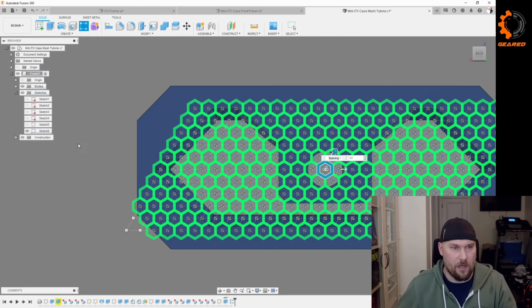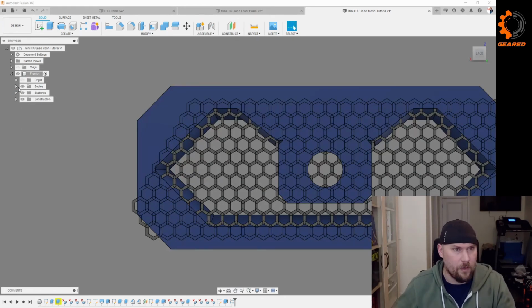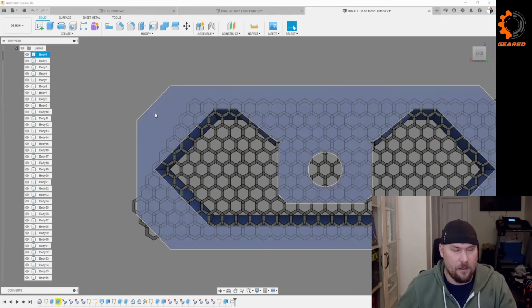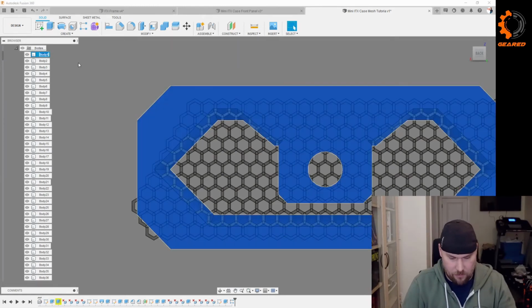It's going to create a whole bunch of bodies over here. So we are going to turn off that sketch. We don't need it anymore. Collapse that. And then we're going to expand out bodies. And we have a lot. To make it easier on ourselves, we're going to rename this first body to face.